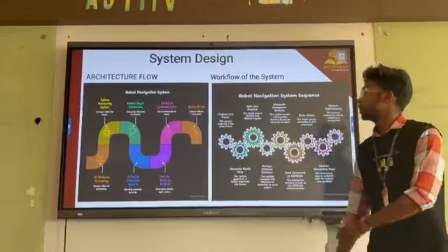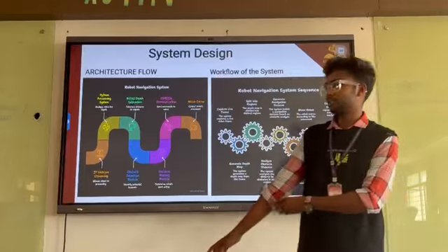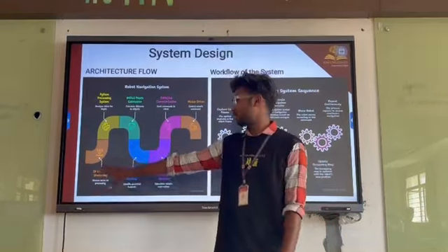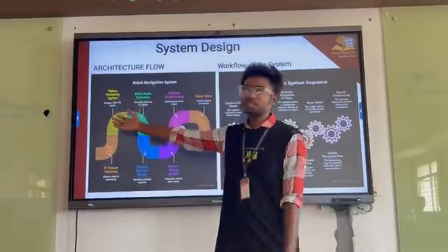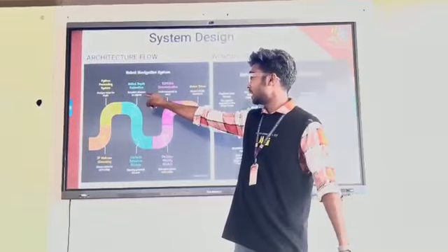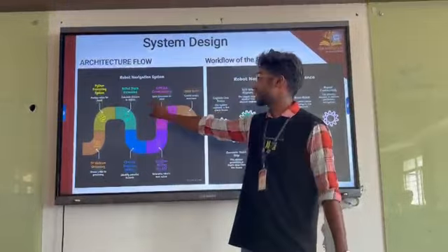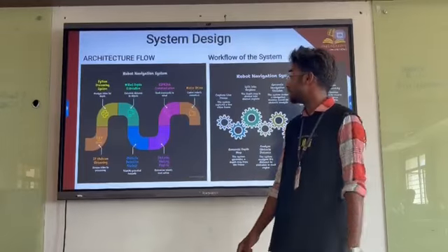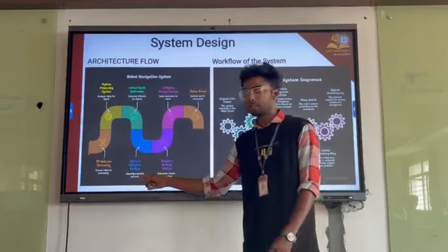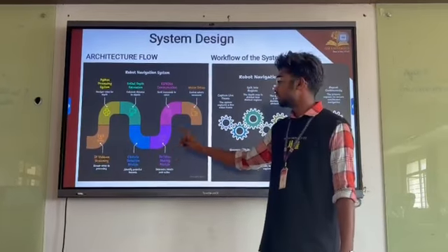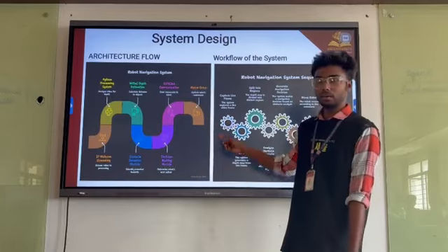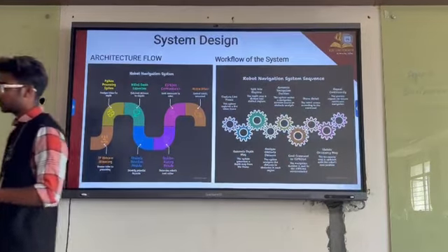Thank you, Rohit. Coming to the architecture flow, as said, we are using IP webcam, a pre-built app to collect the data or the frames. Next we are using a deep learning model in Python, called MiDaS depth, which stands for monocular depth estimation. That model detects the obstacles in the path and then makes the decision. Then the decision will be sent to the ESP8266, and then the motor will be driven. I will be showing how it works.